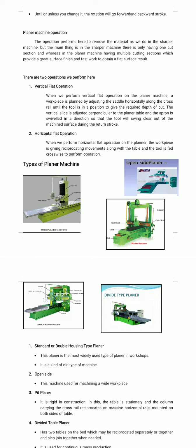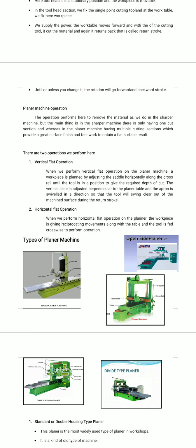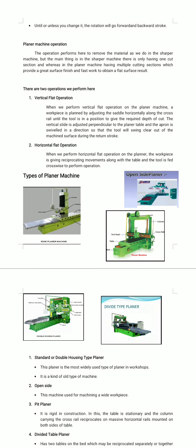Horizontal flat operation. When we perform horizontal flat operation on the planer, the workpiece is given reciprocating movements along with the table and the tool is fed crosswise to perform the operation.